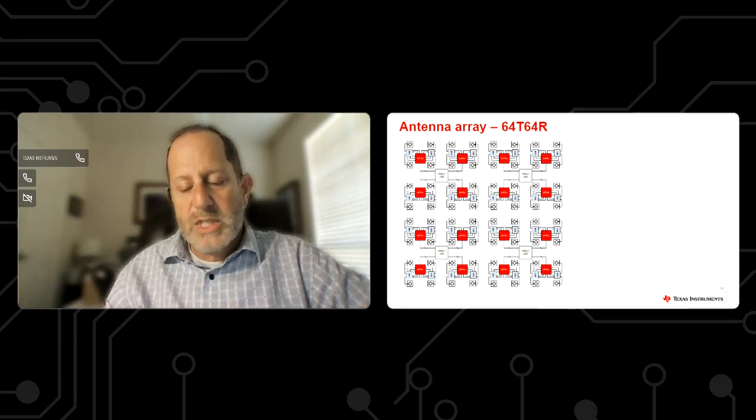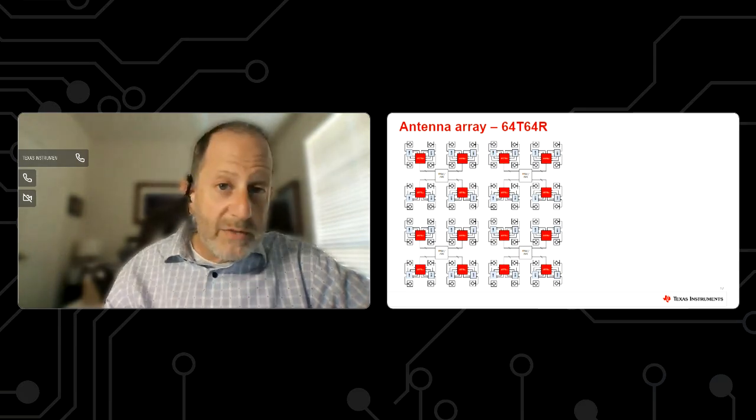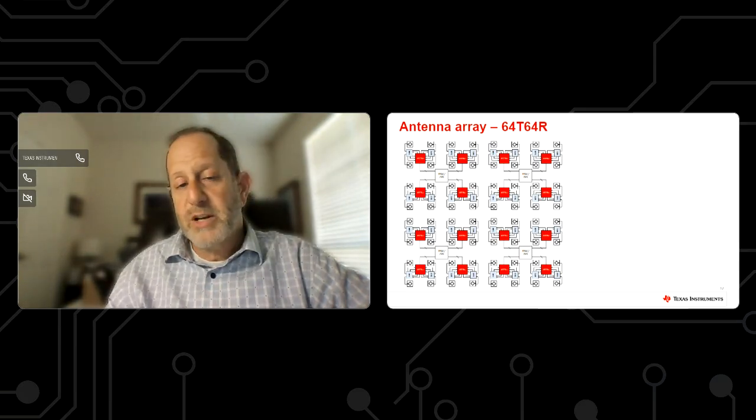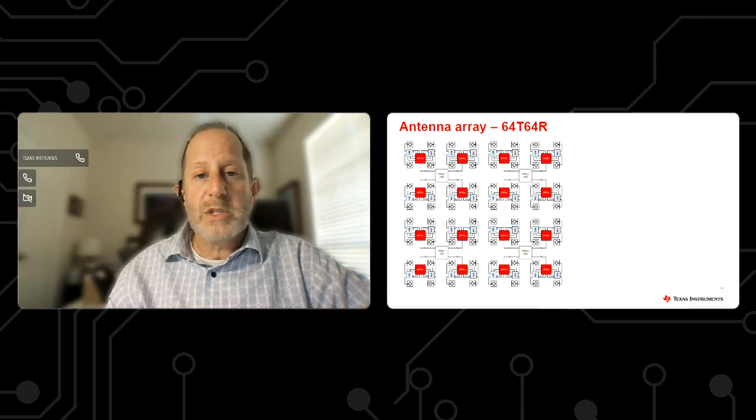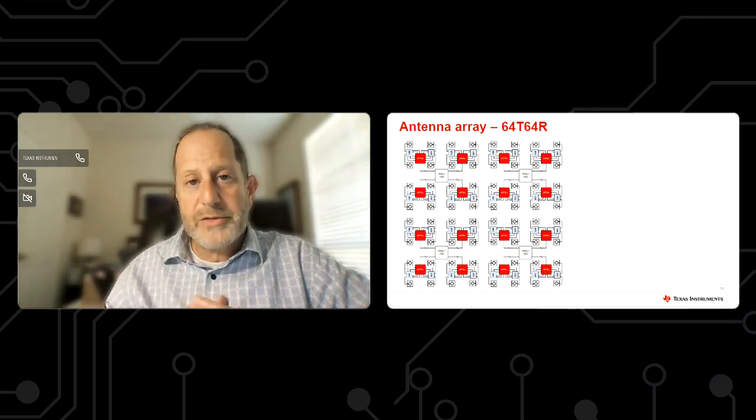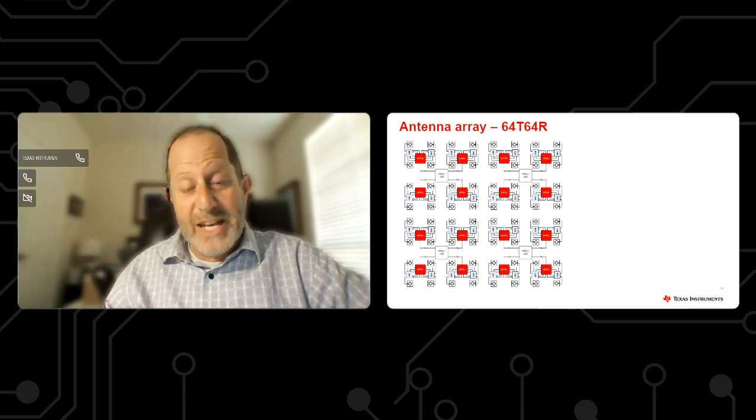So Megtron 6, even for industrial applications, it's a good material, relatively low cost, fairly well available. It's a low loss RF. Can support the high frequencies for RF with low loss, but it also has the added advantage that it's also good for space applications. So that's been our go-to part, certainly for the analog RF boards.